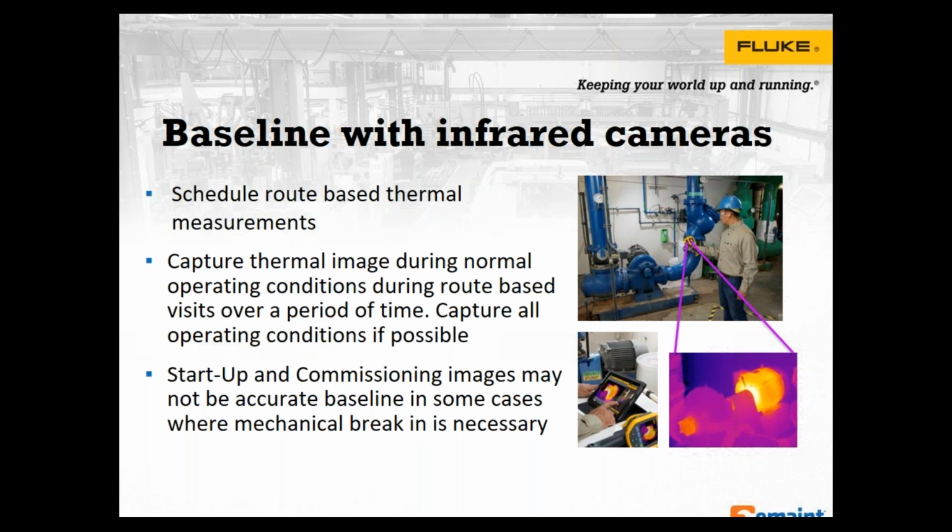So in these cases, you're going to go out on a routine and take scheduled, route-based thermal measurements. Things to consider: is the point of reference taken at the same point every time? I've seen situations where I recommend putting some X's on the floor or some sort of marker showing where to stand and how far to stand away.